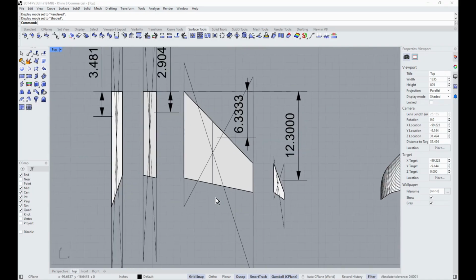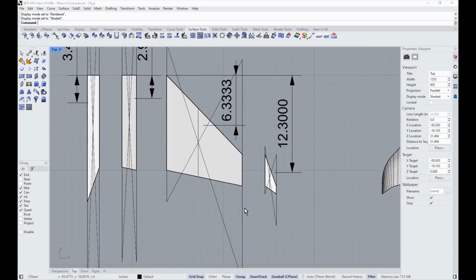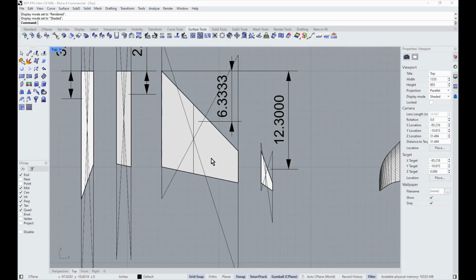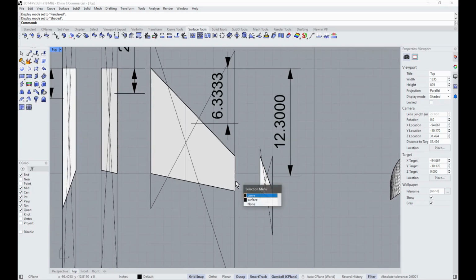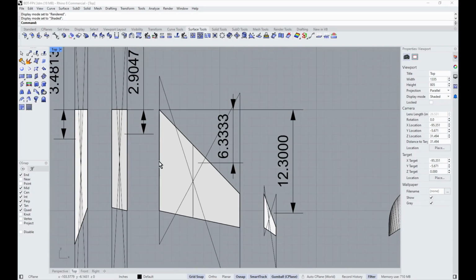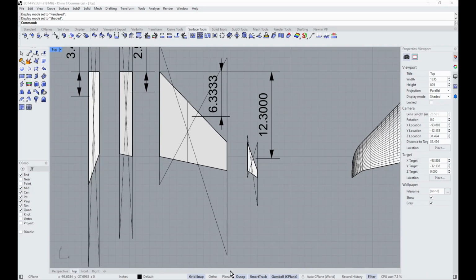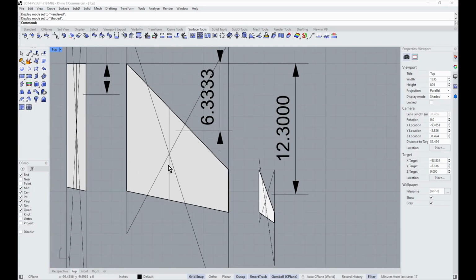So the first thing is what I call the zigzag method. It's a geometric way to calculate the mean aerodynamic chord for a tapered wing for a particular section. So let's just say this is the biggest section right here. You would take this tip chord, as shown here, and you would copy it to over here and over here. And this root chord, you copy it from over here to over here. You cross them like so. You draw a line going down it and you trim it to the leading edge and trailing edge. And that would be your mean aerodynamic chord.